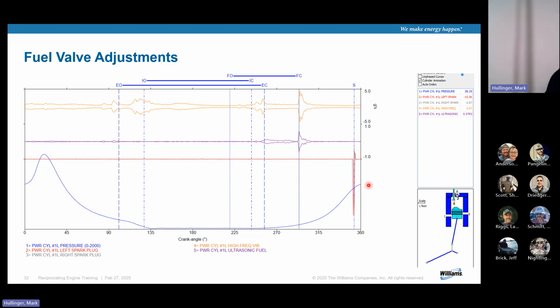Mainly because we can. If you look at the pressures right here, the pressure's not that high, and combustion starts to happen. And then right over here around 22 degrees, 18 to 22 degrees, that's where we get peak pressure. And then finally we get the kick or the push that goes down on the crankshaft. And that's where the horsepower is made. Okay. So the higher this pressure, the higher the force pushing down onto the crankshaft, right? And you want it to be spinning. You don't want to hit it right on top.